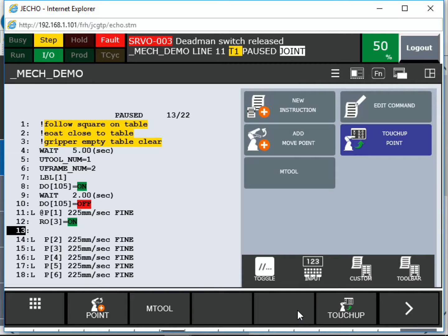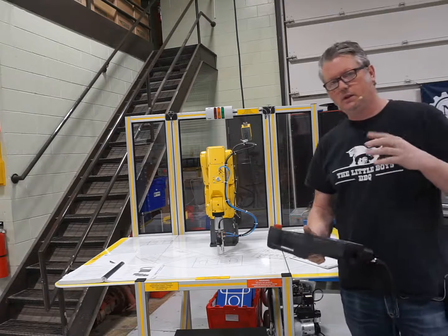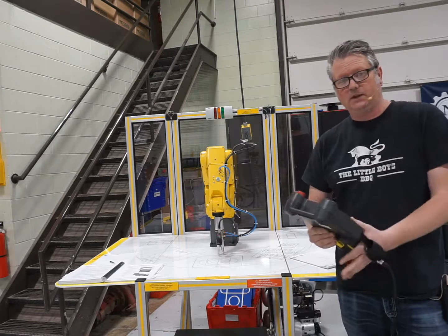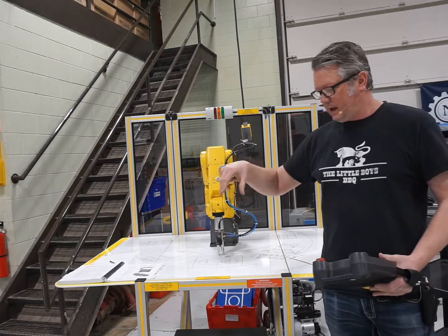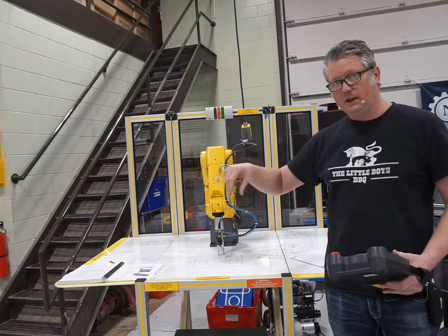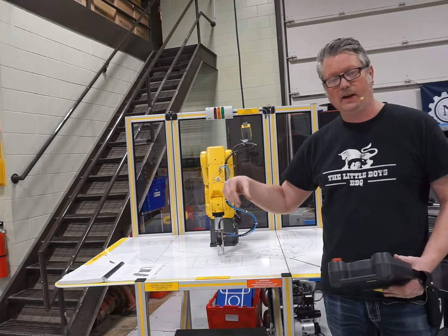And sometimes it's interesting that you've told the jaws to close, but there's a small delay. So I've seen it happen before where the robot jaws will open and close, and then it didn't actually grab the object. So it's important sometimes with pneumatics especially that if you wrote this program to have the jaws close, give them a little bit of time to actually close and clamp down on the object that you're trying to grab.